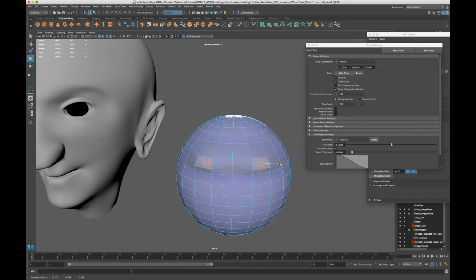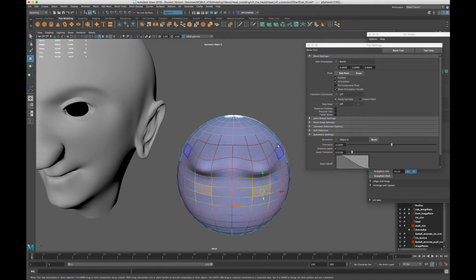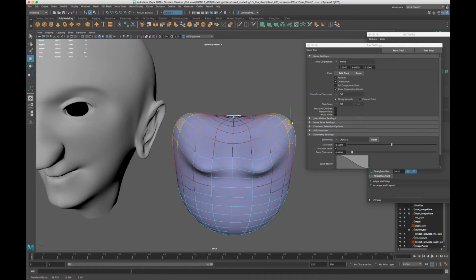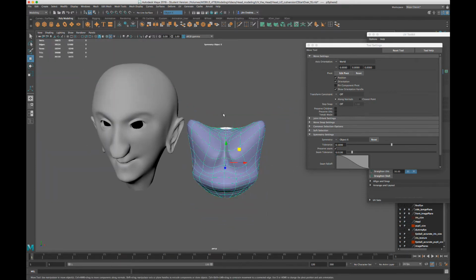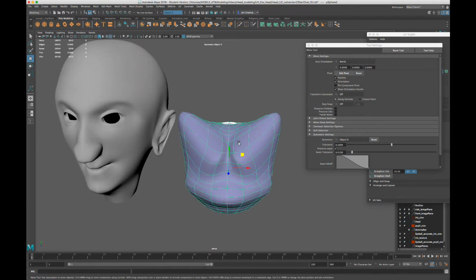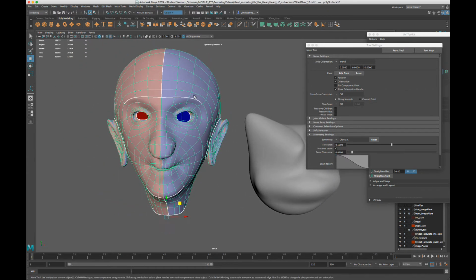for another face is selected. Probably be good for making eyes or ears coming out symmetrical. Could be a preferred modeling method. Well, it goes to take it for granted perhaps that this requires that your mesh is perfectly symmetrical. So one side has to have the exact point value that the other side has. So this particular mesh is slightly asymmetrical because of the work I did on some of the left eye versus the right eye, and a little bit different here and there.